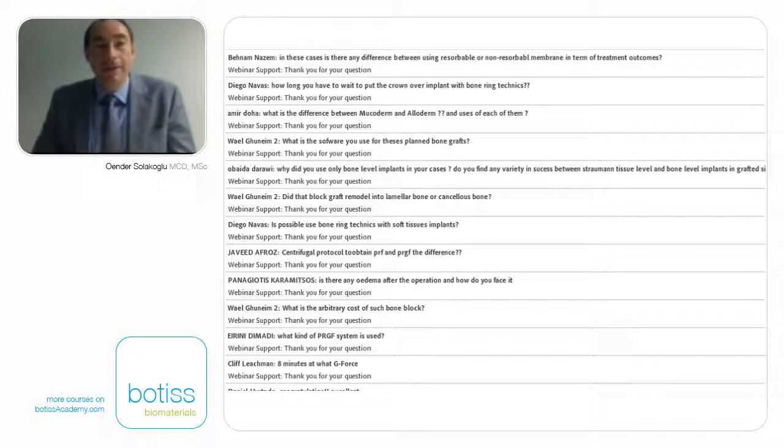So I think the easiest way to obtain the correct protocol is to contact the individual company and discuss with them which centrifuge you have, because there are so many different times and speeds that you can use, so that you really have to make sure that you have the right protocol for your centrifuge. And we tried it many times, and now we have the correct protocol, and it's about 8 minutes of centrifuging at 540 G. But this is very specific for our centrifuge.